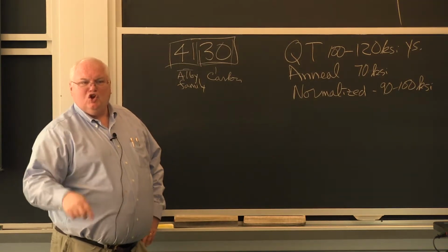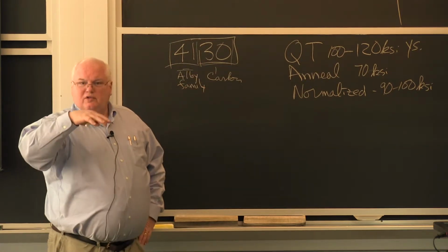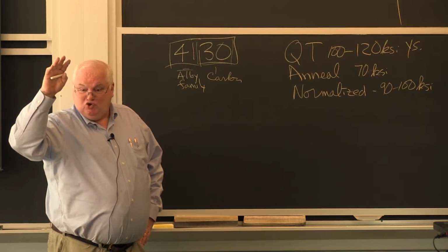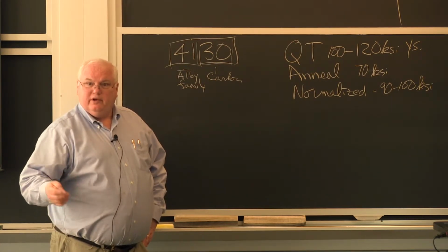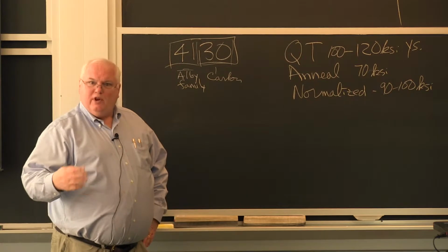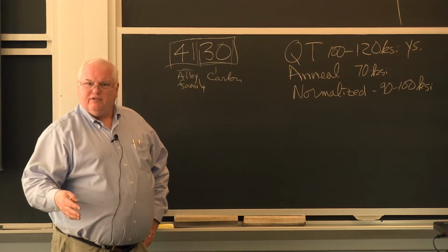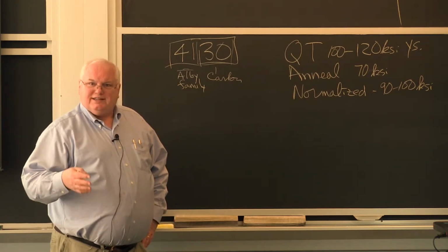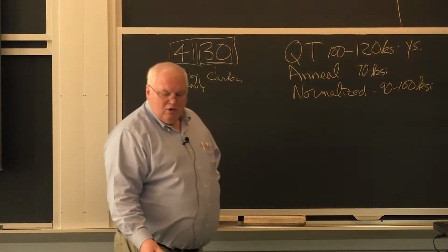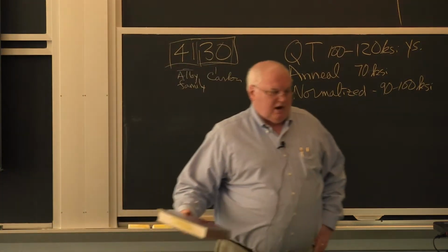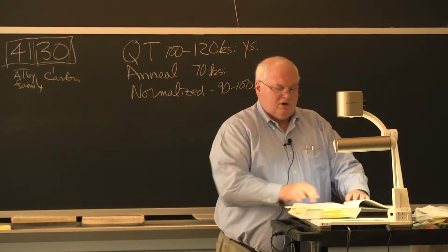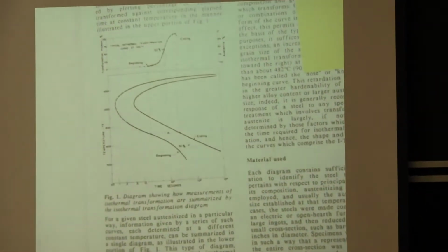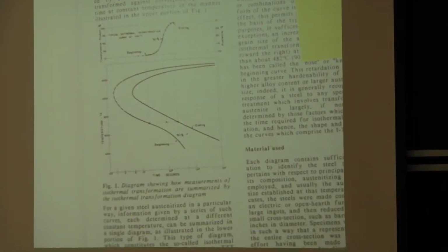You need something to slow down the transformation because the thing doesn't cool immediately when you put it in water. It takes a little time for the water to, you know, when you first put it in the water, you get boiling heat transfer on the surface, and that's not very effective. It takes a little time. It takes seconds for this to occur. And I don't always have seconds, okay? If I start looking at a steel transformation book, and I'm sure you all have these. I had this at home until I brought it in.